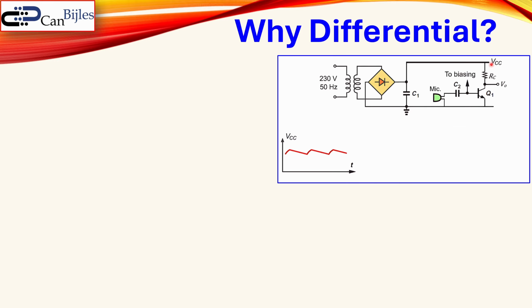Well, we assume that our DC power supply VCC is a constant. So let's say it is a constant value, let's say 10 volts. Well, in practice, it has some ripple in it, and that might cause some problems at the output. And that problem is actually that we have two separate paths that go to the output. So we can identify, in this case, two components in this amplifier, which is a common emitter amplifier in this example. But the same applies also for the common source amplifier.